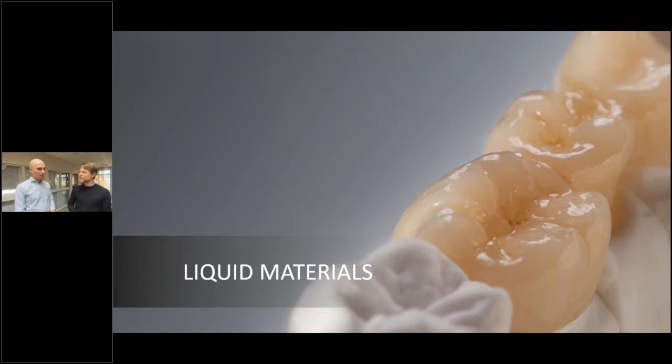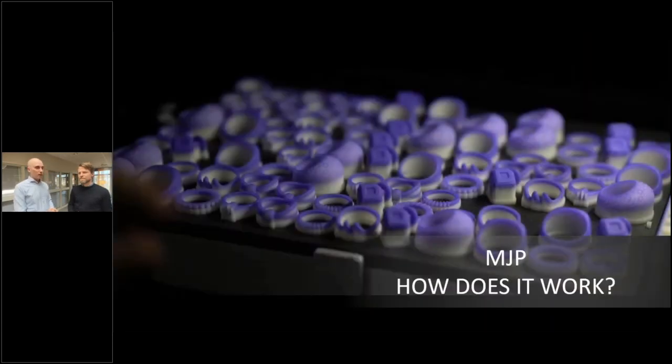So again, under liquids, we will present 2 different technologies, each with its own benefits and users. The first one is called MultiJet Printing, MJP, which is 3D Systems technology. You can see some of the parts on your screen right now. How it works is that you have quite a big print head, and then you apply droplets onto a build plate, both wax droplets, which is the support material, and also a plastic material.